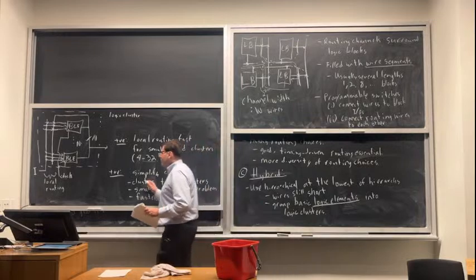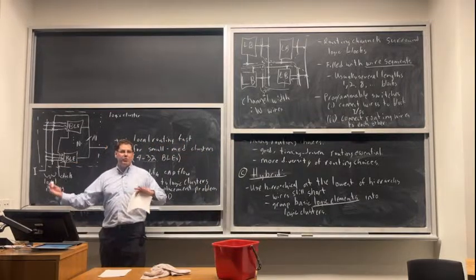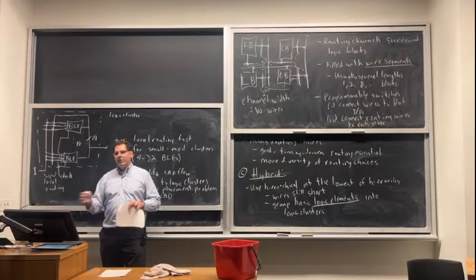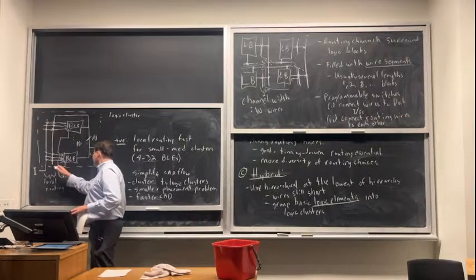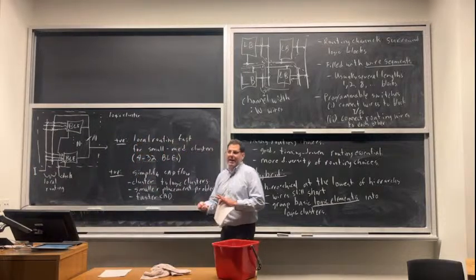Now, you could potentially still get this CAD speed-up benefit without logic clusters by just grouping together parts of your circuit and choosing to place those in certain regions. But it's easier to do it if the architecture really has these clusters because they give you a natural boundary to group things together.